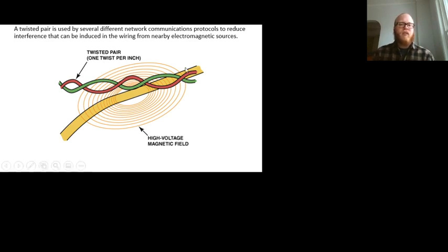And even just things like this cable could be going to a power window or maybe the starter motor. And you can remember when we measured the current flow to the starter motors, we used an inductive amp clamp that clamped around the wire, and it picked up the magnetism created by current flow. And that magnetism could interfere with the little Morse code signals that the modules are sending each other, because the modules aren't really producing any current flow.